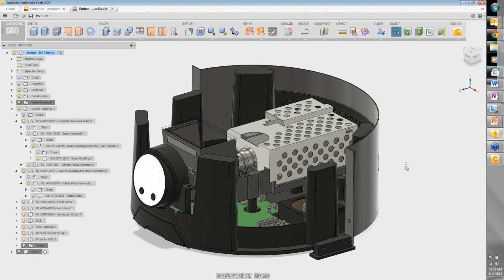I think the thing that I would do also, if you have a Revit model and you're wanting to know diagnostically, you can go into the model assessment toolkit with the Revit model directly, and from there you can see if it's stuff that you would want to fix in SimStudio Tools, or if it's fine, and just move straight from Revit into CFD. But if you're going to go into SimStudio Tools for that workflow, you have to do an ASIS file.